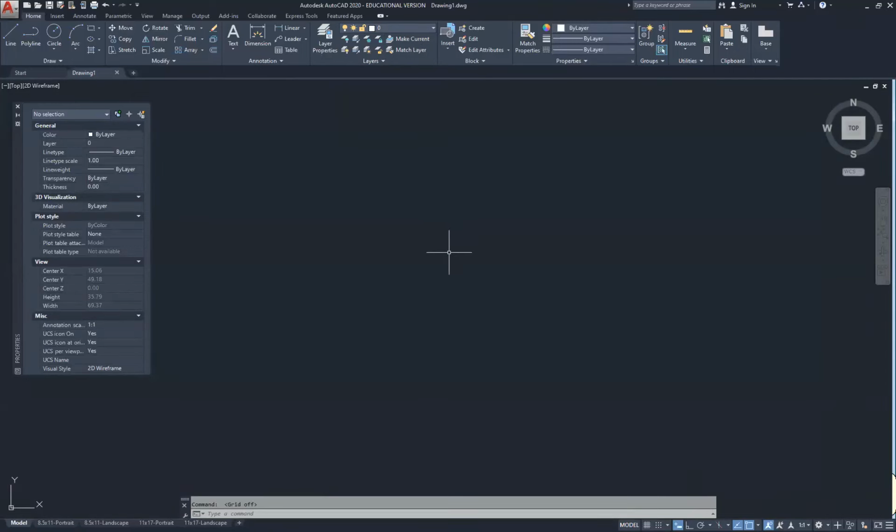So for example, if I want this line, I have to draw a big box across this line to use this highlight tool. If I go the other way, I only have to touch it, like this, to select it. Once I've done that, I right click, and I can now hit the delete button, and that removes that line.